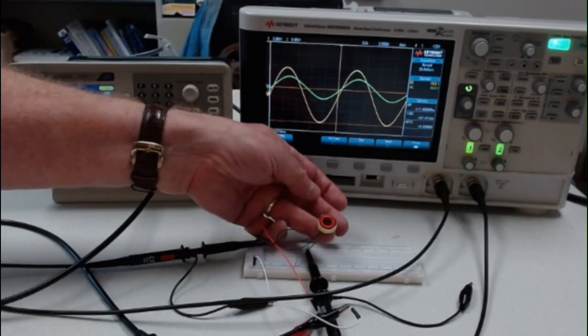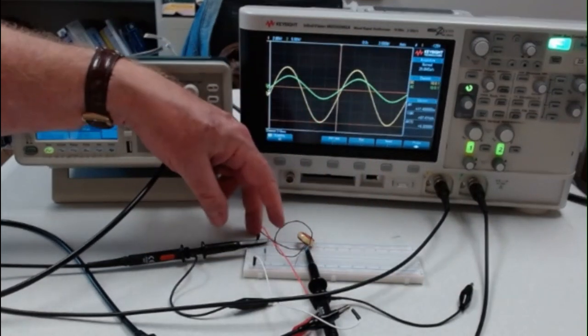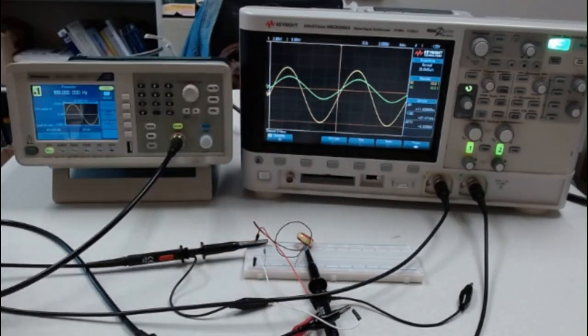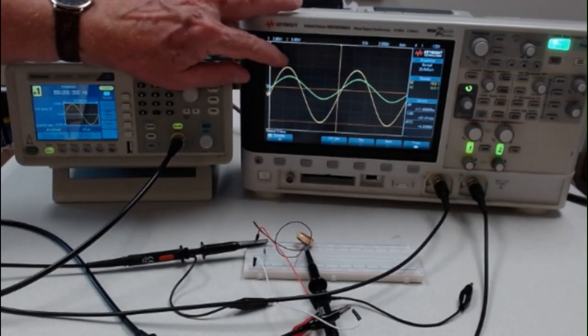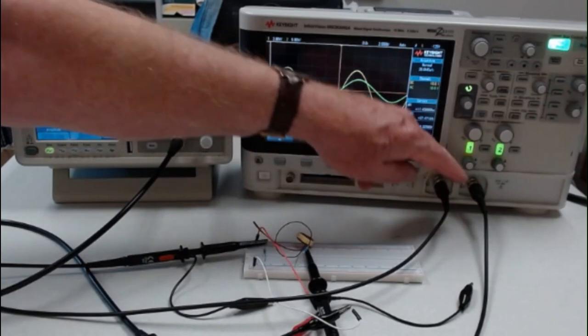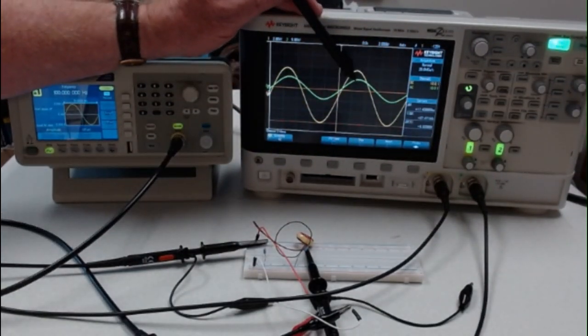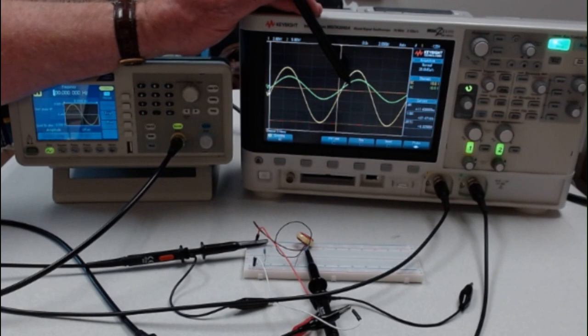Here is our physical inductor. And here is our input signal, the signal in the yellow. The yellow is the input signal, and the green is our output signal. That's from the second channel, and that's the signal coming in as our output, the value across the 10K. So in this situation we're looking at voltage across the 10K, and we're asking what it is going to be doing as we go up in frequency.